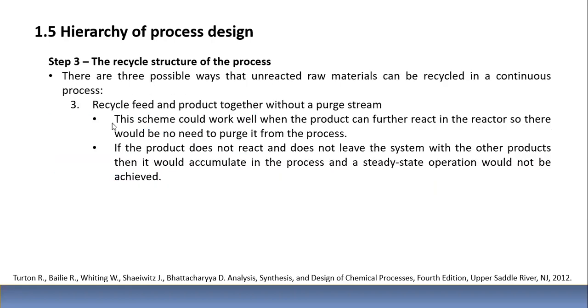Number 3, recycle feed and product together. I think we saw that. This scheme could work. Recycle feed and product without a purge stream. This scheme could work well when the product can further react in the reactor, so there will be no need to purge it from the process. If the product does not react and does not leave the system with the other products, then it will accumulate in the process, and a steady-state operation would not be achieved.